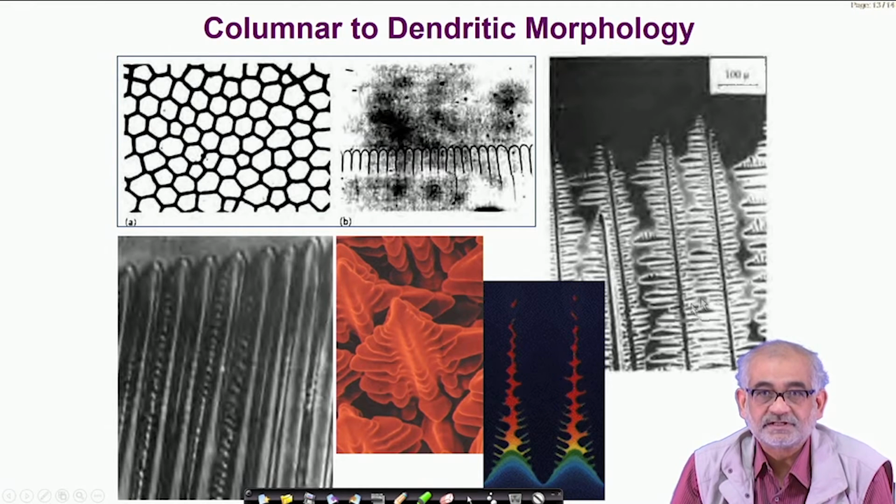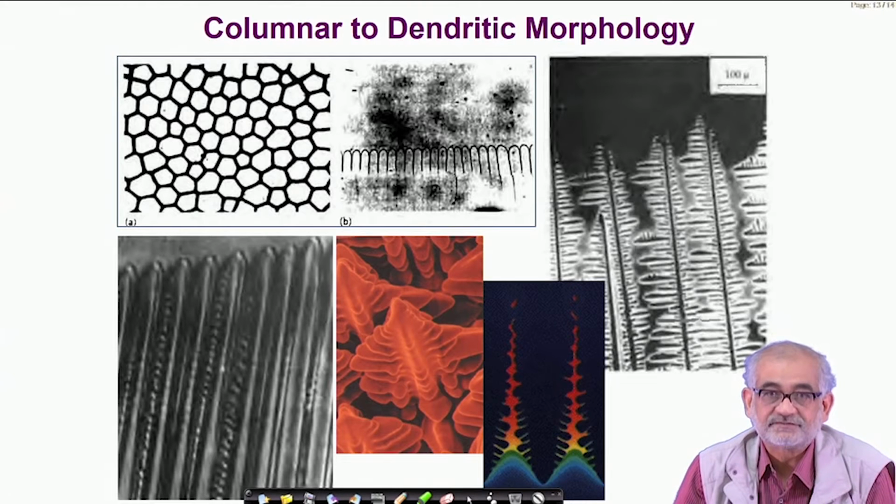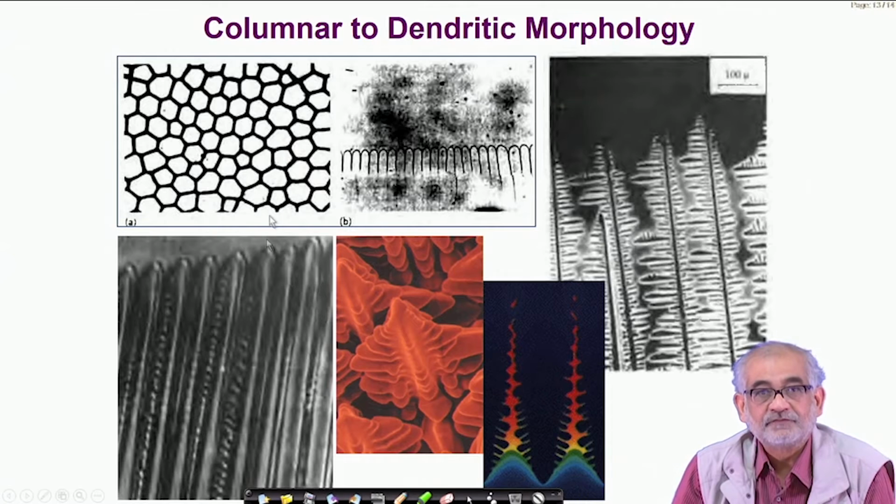So, essentially these either columnar or dendritic structures are typical manifestations of the so-called micro or macro structures that we see in solidified or cast masses. When you take a section of these kind of columnar structures, then you see such very nice equiaxed regions.